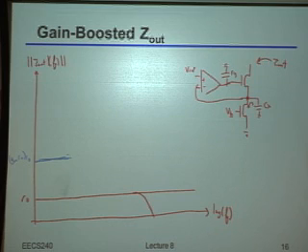What's eventually going to happen to that impedance there? Yeah, there is indeed still a CX. So what will that cause to happen? Yeah, I see hand motions in the right direction. By the way, it's actually slightly tricky, but we can figure this out. So at least one person did something like this. So maybe just say it in words so I can repeat it for the camera. Yeah, it'll roll off. Okay, so indeed it'll start to roll off because of that CX, right?